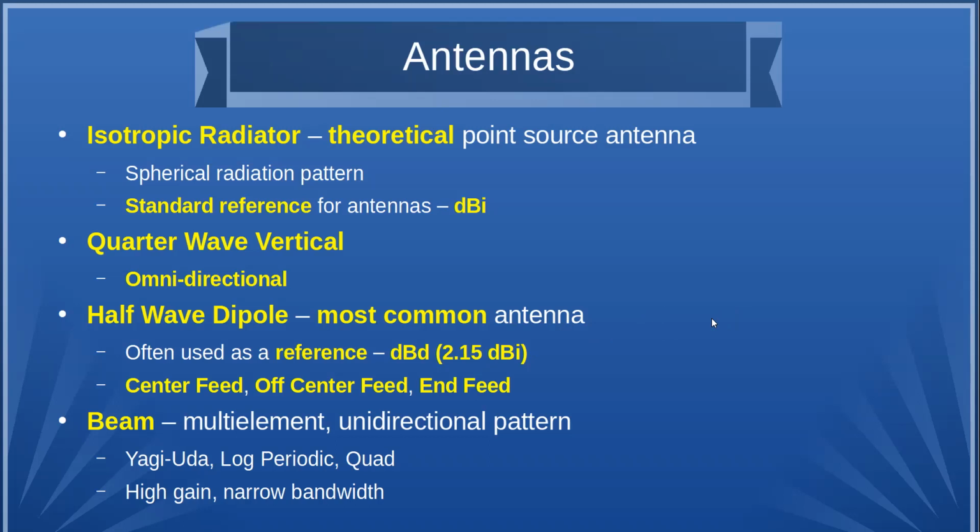And he showed a bunch of examples that he modeled, and depending on height to the ground and inverted, it was anywhere from 5 to 6 dB. So inverted this way? No, inverted V. Okay. It was less, but not that much. He did it even at 60 degrees, which you're not supposed to do. And it was still only maybe a dB and a half less than the straight wire half wave. Interesting. Said it surprised him, and he's been teaching this stuff for years and years.